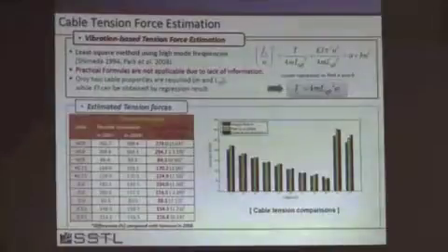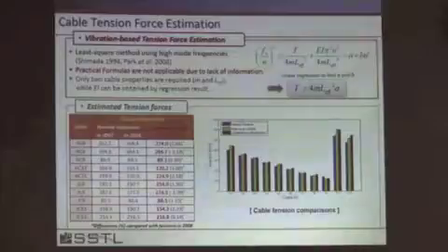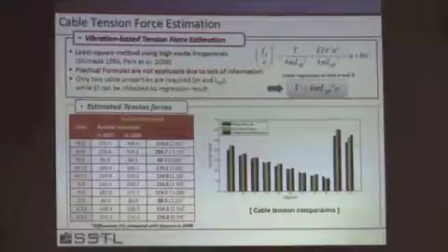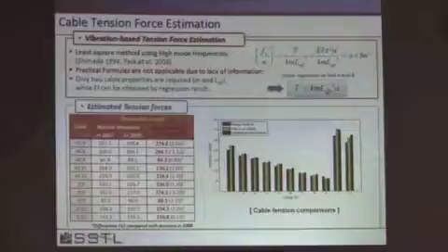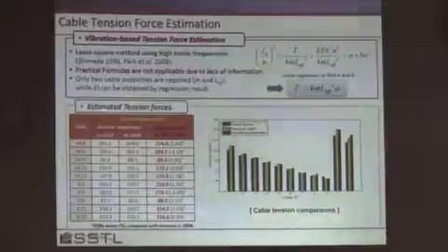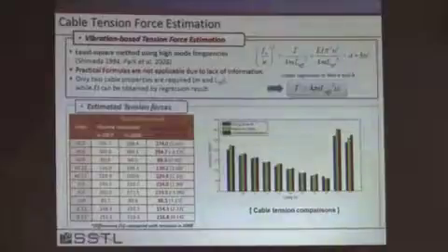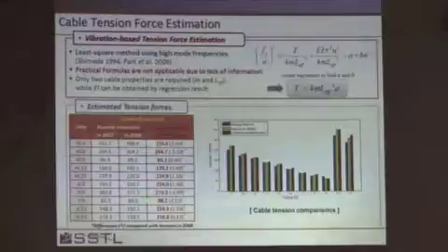And in actuality, each of these cables were not just a simply supported cable, like a pin-pin cable, because they had dampers on them. You remember the galloping vibration problem that I talked about yesterday for these long-span cables? This bridge had a serious problem. So they put dampers, lead rubber dampers, penguin dampers from New Zealand on those cables. And so given that the bridge had changed from 2007 and 8 until 2010 because of the dampers being put in, and that there was a nonlinear character there, being within a few percent is quite appropriate.